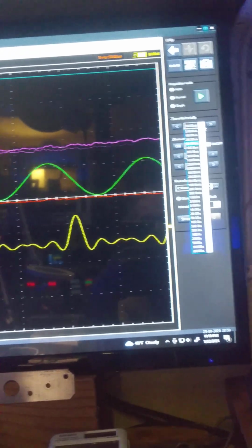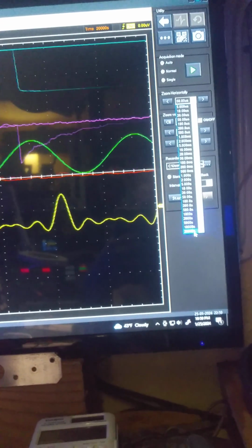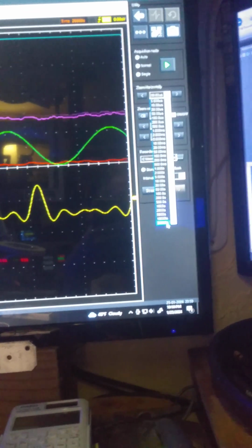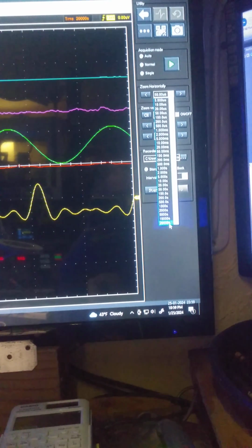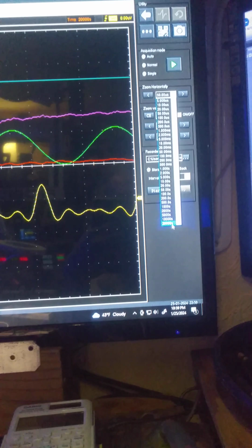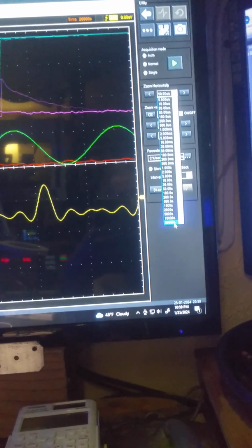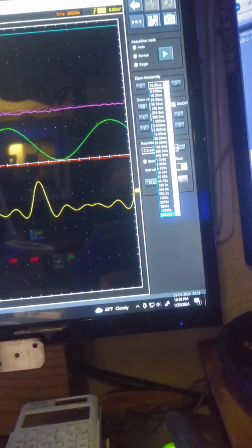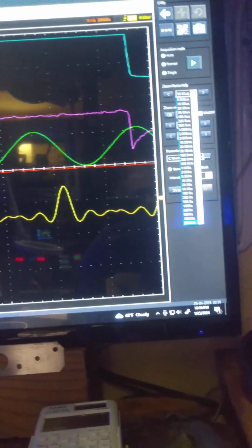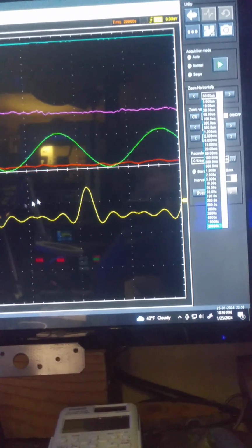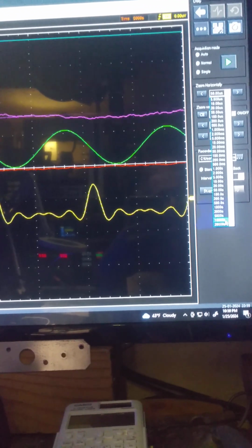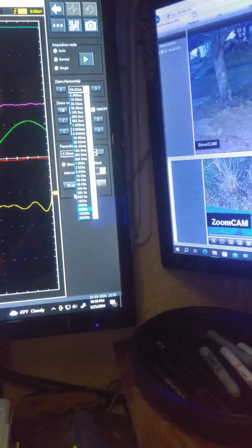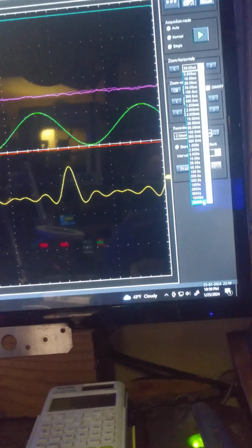This is kind of cool in the sense that you can go up to like 20,000 seconds per division. One of the reasons I bought this was for data logging purposes, but I'm a little nervous that if you had some occasional high frequency stuff, it'll show up as a phantom signal. The lower you set it, it'll alias, I promise you, across all these waveforms.